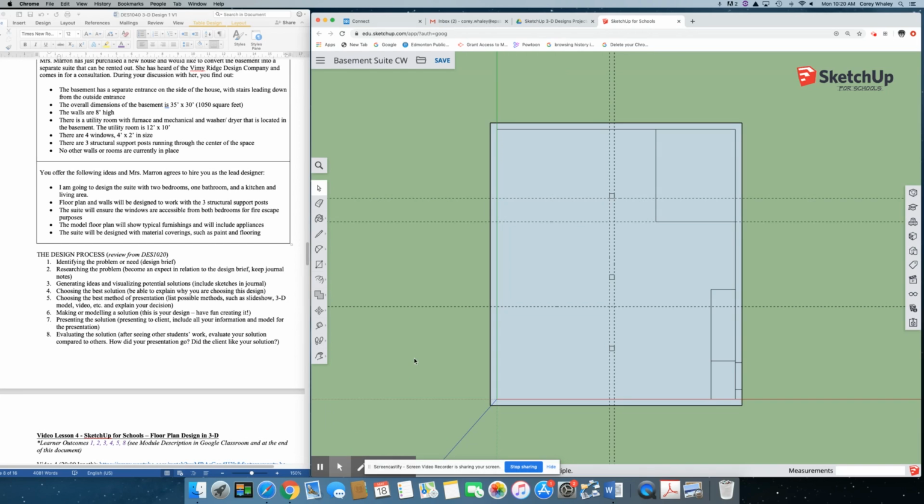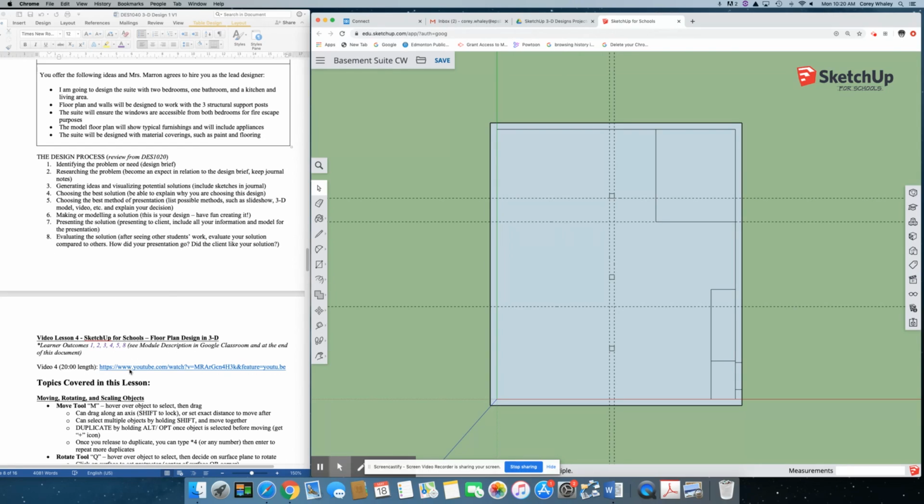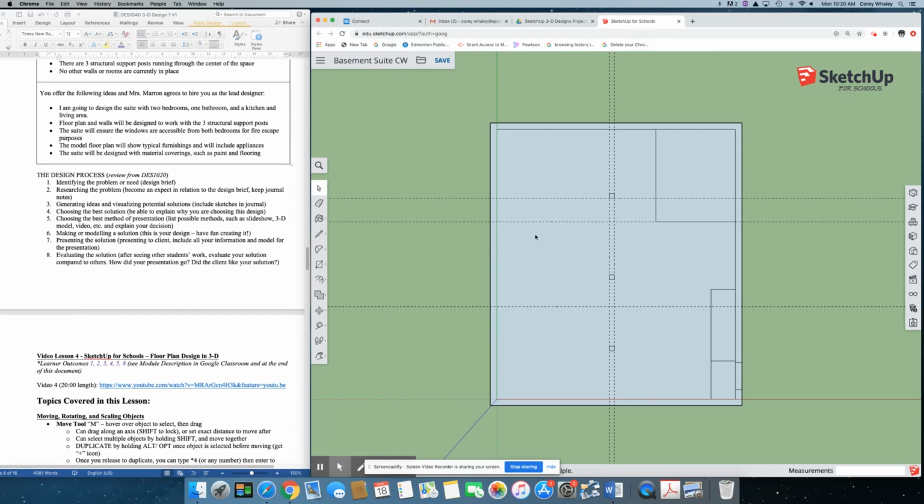Okay, we're going to start putting some walls in place. And I know we haven't gotten to a lot of these topics yet, but we will. So we're going to sketch in some walls now. So we already have our exterior wall. And typically a wall on the interior space of a house would be about, let's say, 4 inches, because a 2x4 would be what a lot of the framers and construction industry people would create the walls with. So 4 inches plus some gyprock, but let's just call it 4 inches. So each of our walls separating rooms need to be 4 inches.